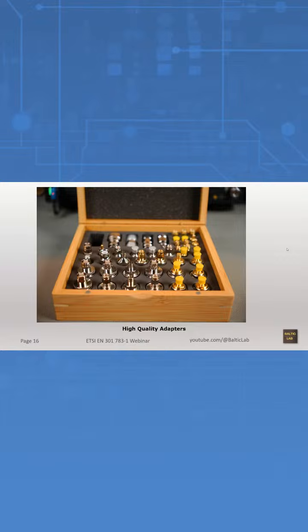This entire set cost around, I think, 200 euros. But these are good for repeatability. You will need that. You have accurate insertion losses on the data sheet that you will later need to correct. And the most important thing is that it's also constant over a broad frequency range. If you just measure at one location, nobody guarantees you that the same behavior is present at, I don't know, 4 or 5 gigahertz. So please do that, or at least verify the cheap stuff you got on Amazon.